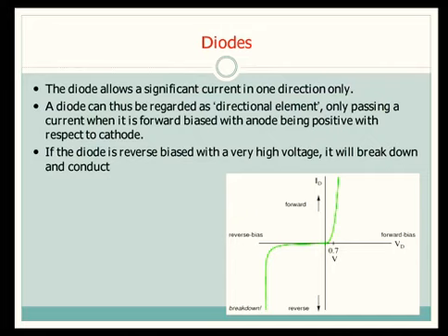The figure shows the characteristics of a diode in forward bias condition and reverse bias condition. The graph is plotted with voltage on the x axis and current on the y axis. In the forward bias you can see that the cutoff voltage is 0.7 volts. When the voltage goes above 0.7 volts, it easily conducts in forward bias condition, and in the reverse bias condition the diode will not conduct electric current until some considerably high voltage. After that high voltage is achieved, it will start conducting.